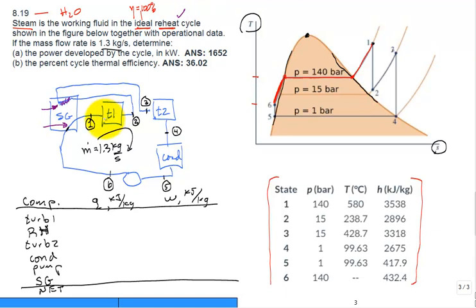What do we have for the first turbine? Well, put in the numbers that are 0 first. It's adiabatic. Well, where did they tell us it's adiabatic in this problem? Well, it's a standard assumption that there's no heat transfer. And if you go to an actual power plant, they actually wrap these turbines in some sort of blanket, insulating blanket, and then when they need to service them, they take that blanket off. I mean, that blanket's maybe, I don't know, 5, 6, 8 inches thick, so it's pretty good insulation.